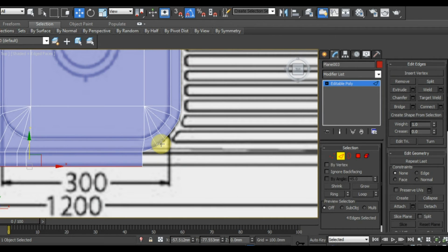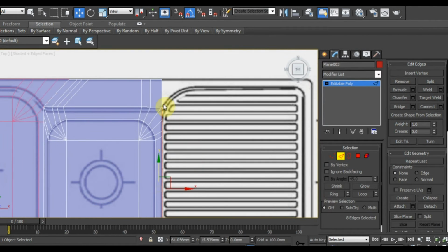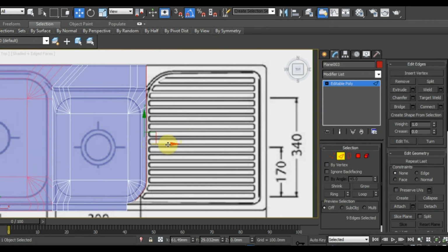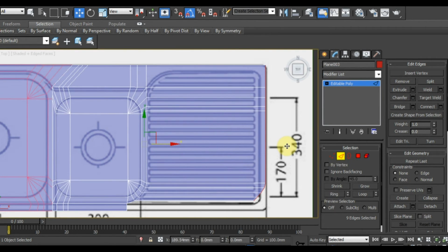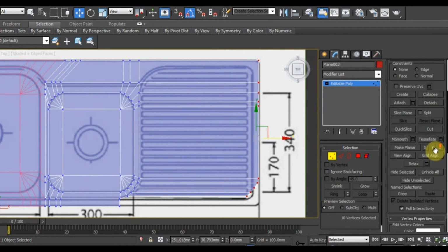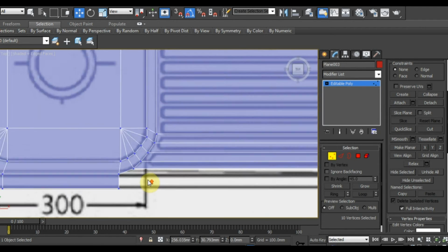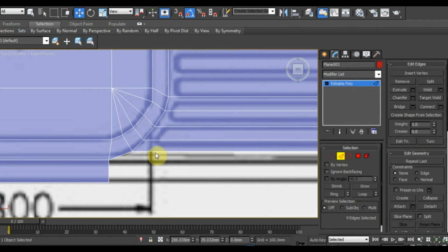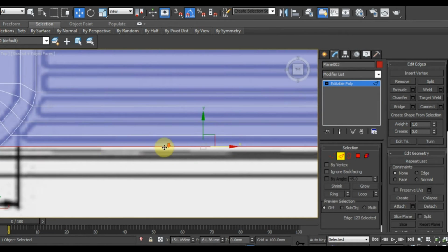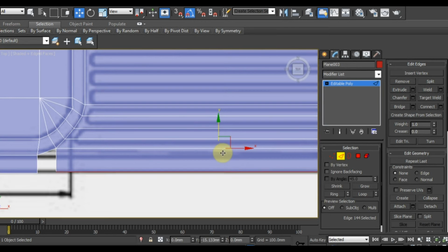So we've got that. What we might do is do the same things. Select these vertices. I might just drag those right out to over here actually. And select that. And we're going to make them all Y. Oops, sorry, Control Z again, X. And you can see I've left one down here because I wanted to join these up properly. So I'm going to select that one edge, hold down the shift key and drag down.